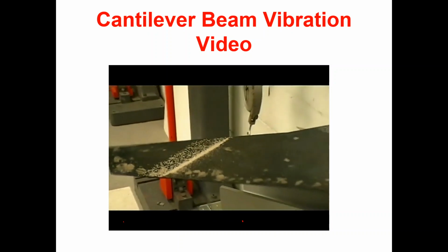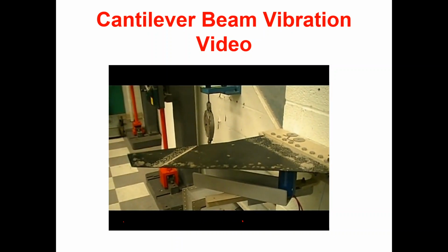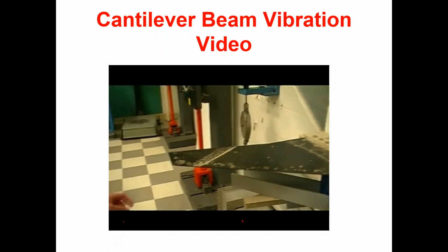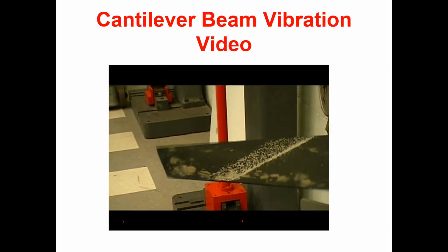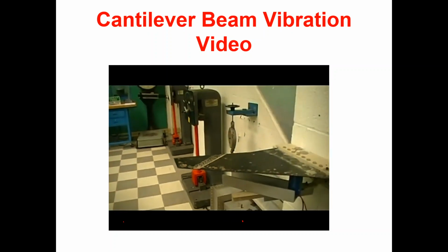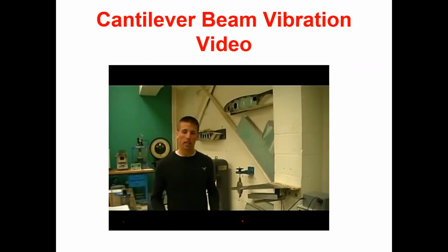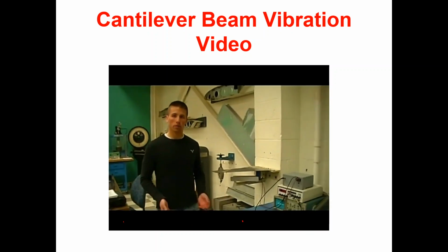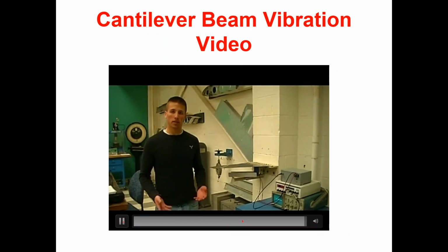As you can see, a nodal point has formed along this line. I'm satisfied that the tip of the wing has reached a maximum deflection, as well as the proper nodal point has formed, and I can now move on to modeling the other modes of vibration that we will be testing. A stroboscope can also be used to get a more exact measurement of the resonant frequency.